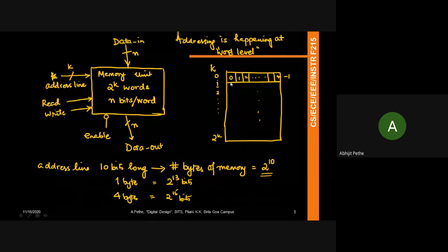So now, physically, if you think about it, this is second order effects which are not expected from you in this class, but when you think about it, in reality, this memory unit is spread on a finite area of a chip, right? So which means that if your data inputs are coming from the top, writing something which is close enough to the data input port will require less time than writing something far away from that data port, because these signals have to travel over metal wires, right? They are interconnects, there are transistors as they travel through. So writing something far away from the data port may take longer than writing something here.